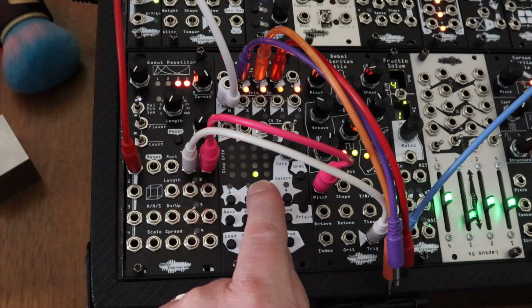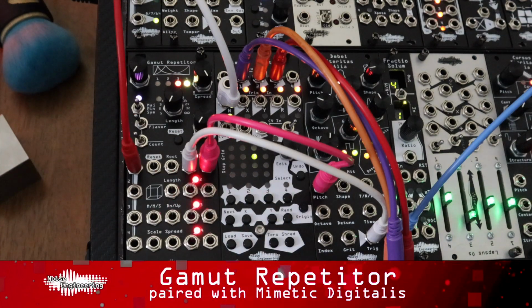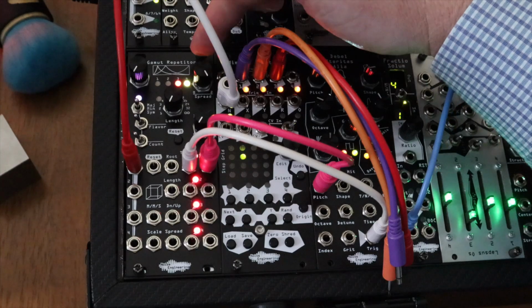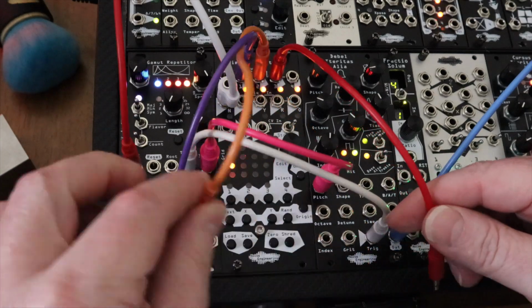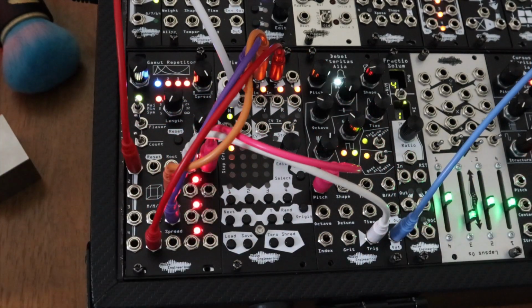The Mimetic Digitalis and Gamut Repetitor go together in so many ways, and here we'll use the Mimetic to control some of Gamut's CV inputs. Set Gamut's length and down-up controls to the left and set spread to the right. Add Mimetic's stepped CV patterns to Gamut's down-up, length, and scale inputs to give random yet structured loop patterns.